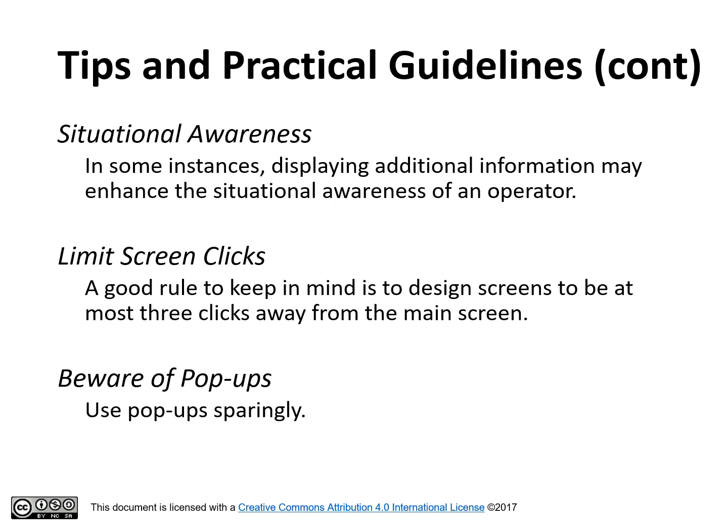Situational awareness. In some instances, displaying additional information may enhance the situational awareness of the operator. Line charts indicating a historical trend together with the current value of a process variable may provide an indication of an upcoming process abnormality to the operator.